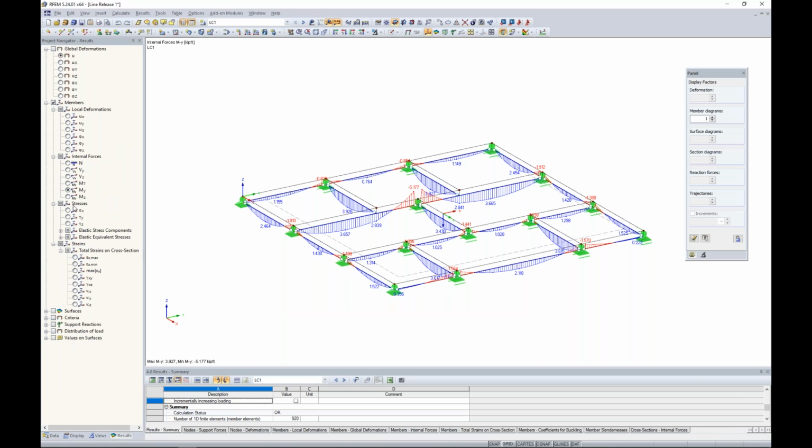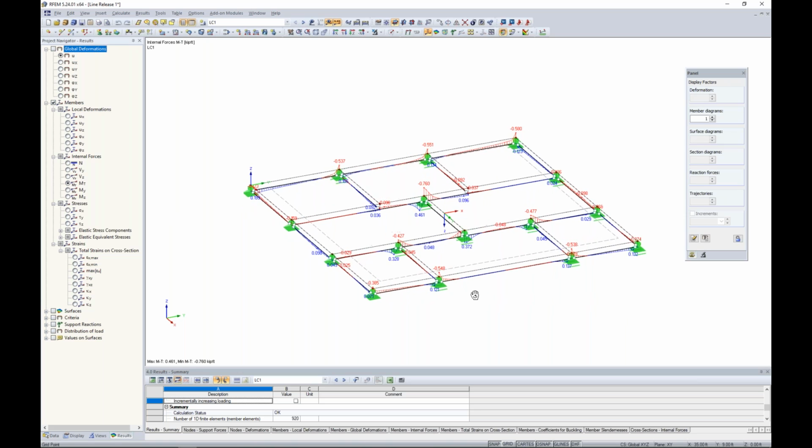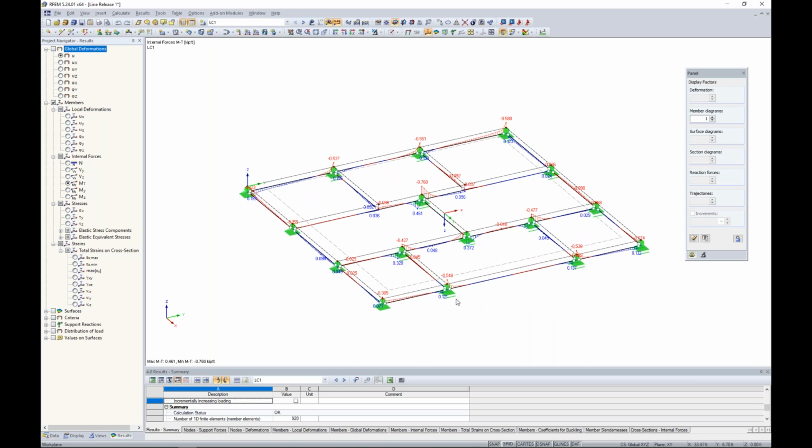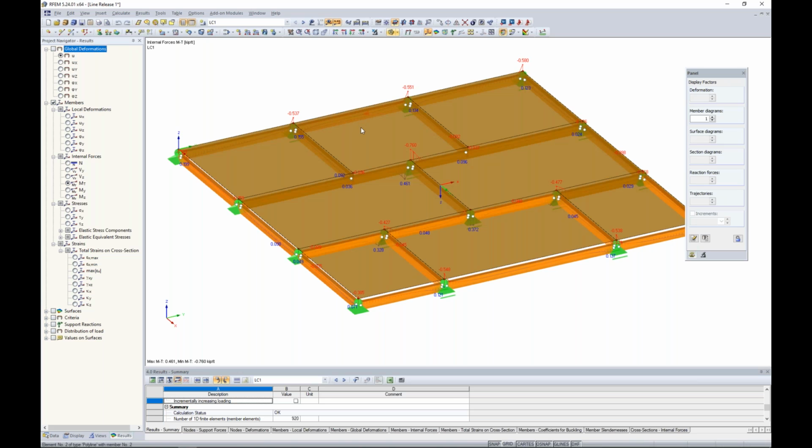And when I take a look at torsion, for example, we're seeing some pretty high torsion forces within the structure, and this definitely is not ideal. Typically, when we are connecting the CLT floor to the beams below it, we're going to use a screw type connection, and the screw is going to release the moment so that we're not so concerned with torsion in our members.